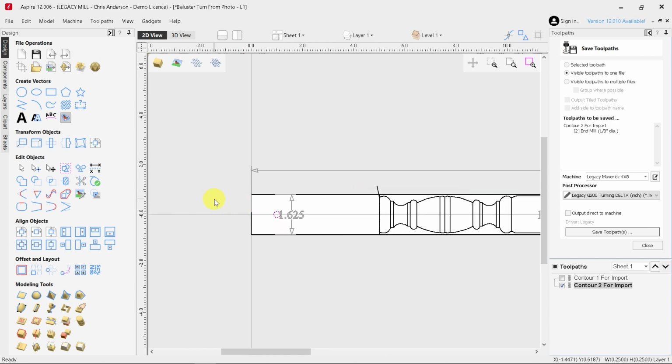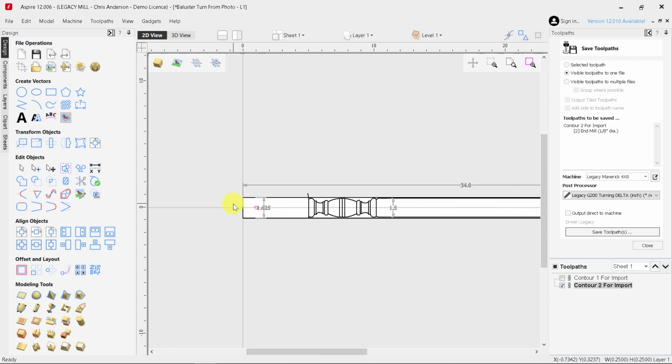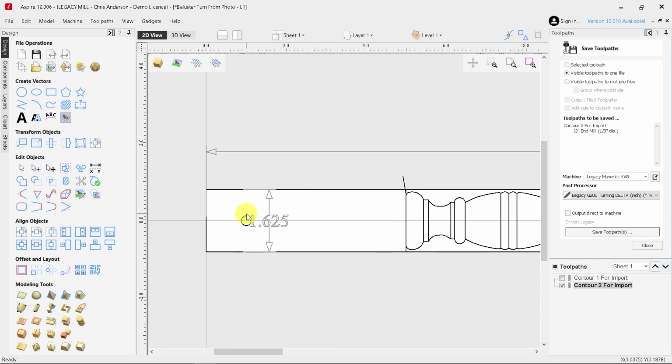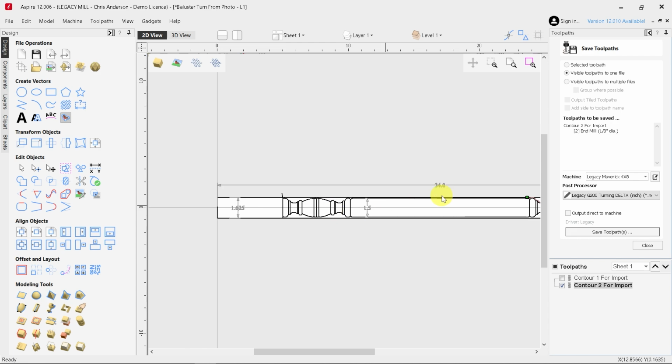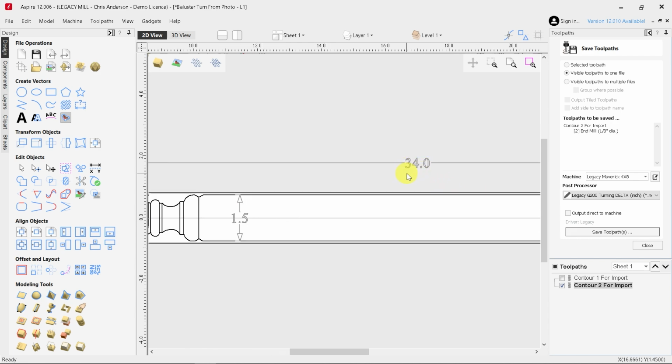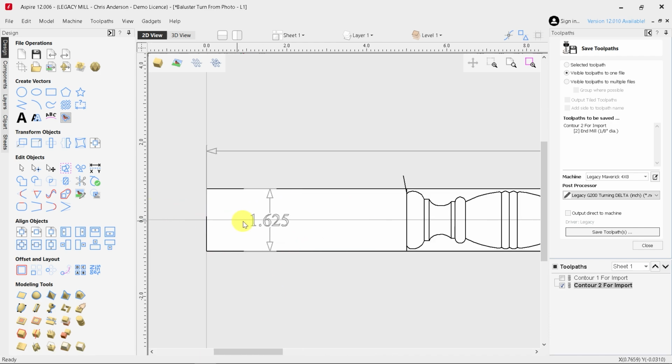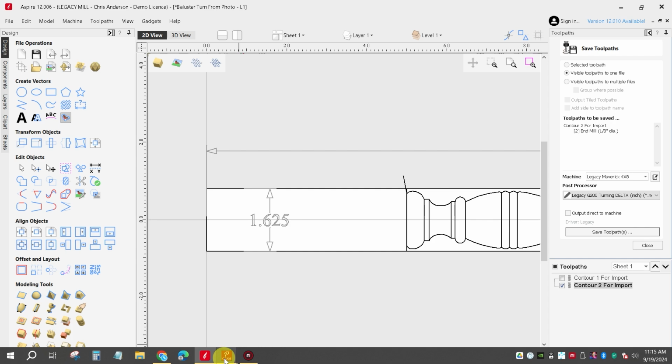If I add an extra inch here in the front for my fixturing, that will accommodate how I'm holding it in the machine, and I can still keep these parameters in play. So I'm going to add 1 inch to my blank size. Instead of 34 inches, I'm going to use 35 inches, again because of where my X0 is located on my system.